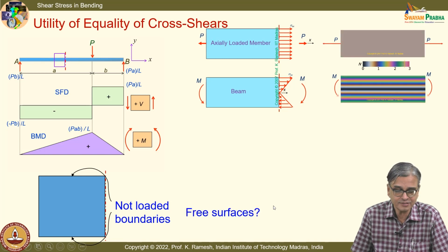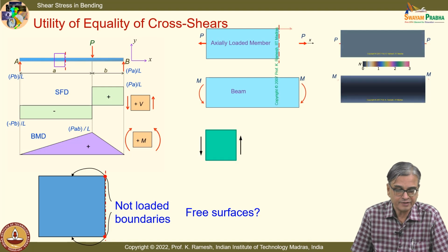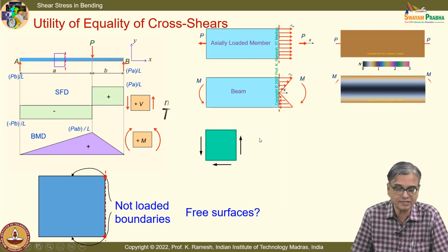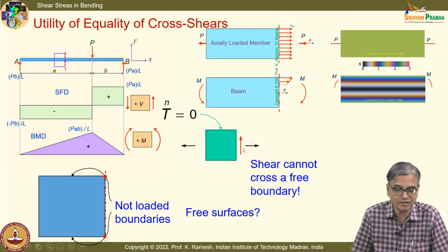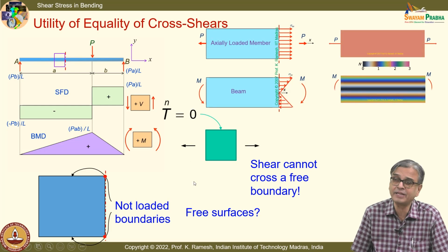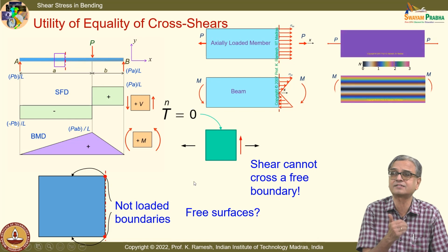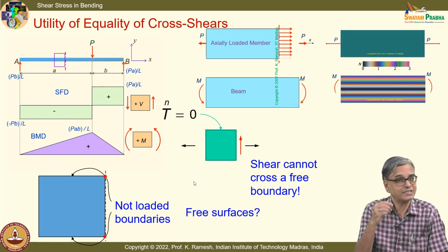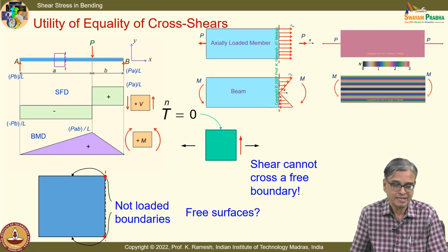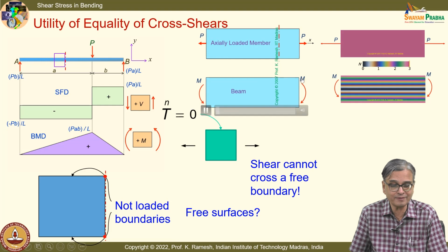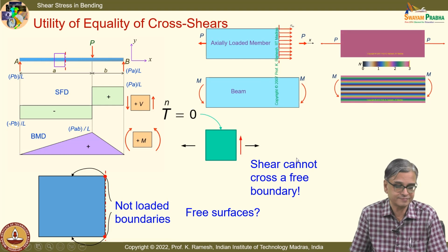Our logic was, it was a free surface, there is no shear acting on that, and we said that this shear force is not acting because it is a free surface. So all the other shear stresses go to 0, and we also raised a question, can it support a horizontal force in this plane? All that is happening in the cantilever beam as well as this 3-point bend beam. We have seen shear stress is 0 at the top point and at the bottom point,